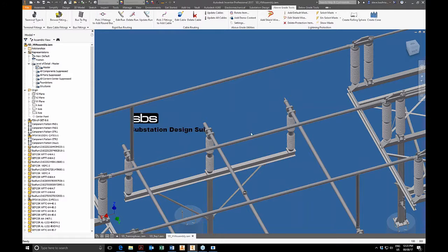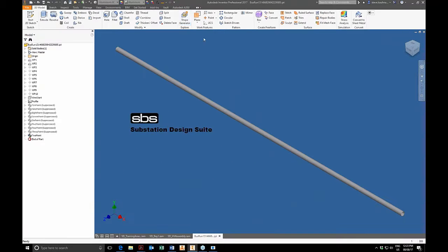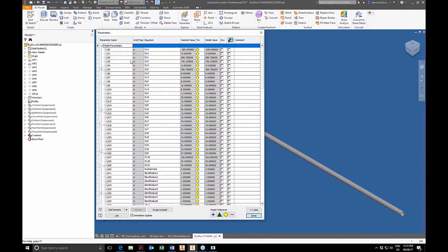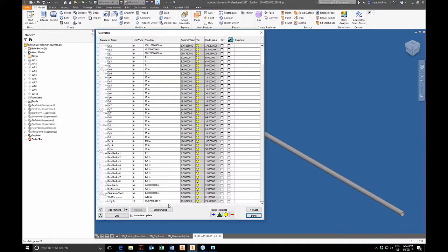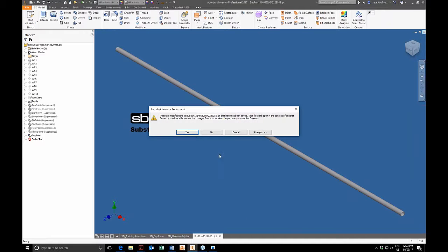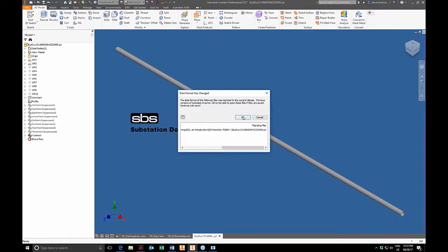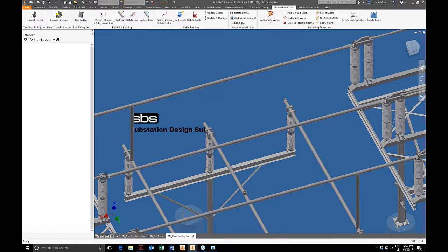And there's my bus. Like the cable we looked at earlier, where the cable was identified in the lengths and totalized, this is doing the same thing. If we look at the length of this piece of bus, it's 29 feet long. This gets totalized as well in the bill of material, so you know exactly how much bus you're using for this size of bus. The part numbers and stock numbers and descriptions can all be edited, and that can be done in the database setup.